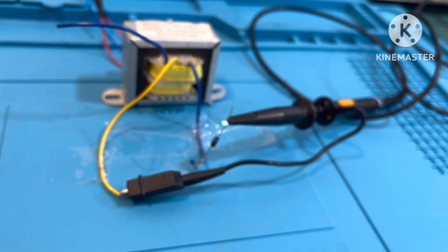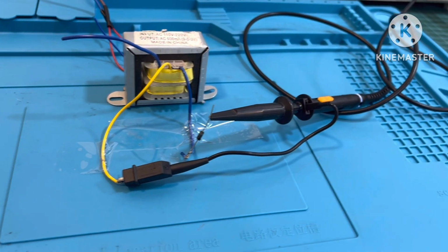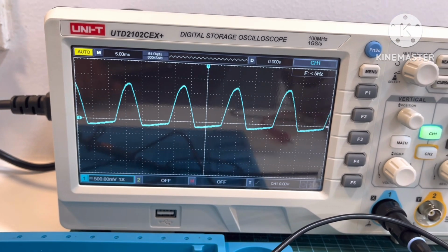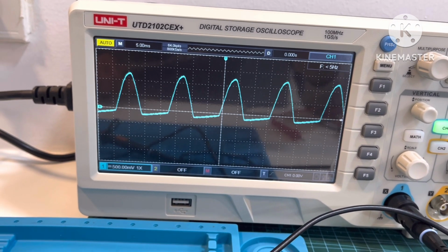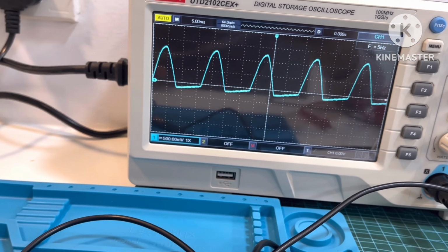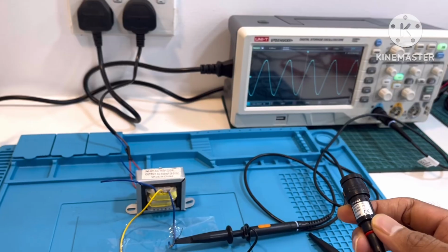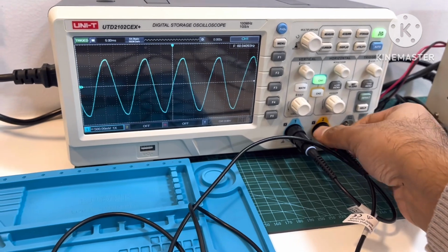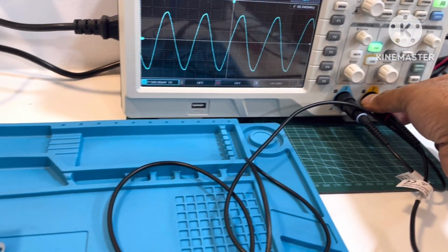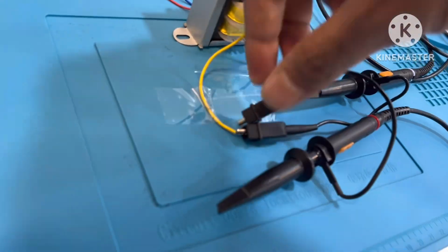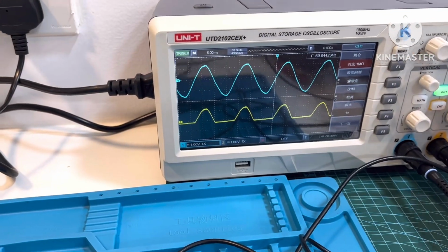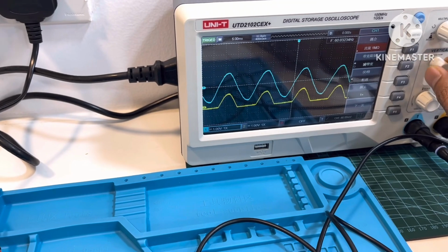I connected the diode in forward bias. So now I will check the signal on the oscilloscope. You can see the voltage has been rectified. The negative half cycle is cut off. Let's connect another probe before the diode to see the two signals together in the same plot. So after calibration we could see both the signals in the same plot.